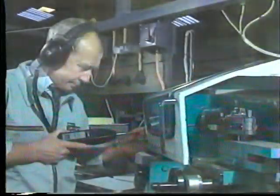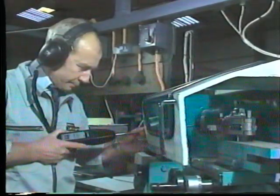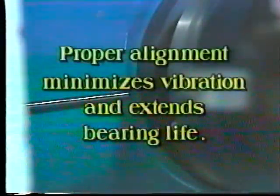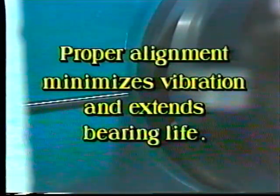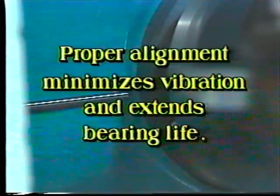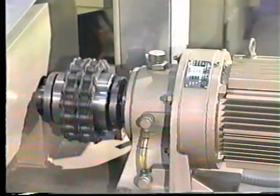One of the factors affecting coupling selection is the speed at which a coupling has to work. High-speed applications usually require couplings that can be precisely aligned, especially when there is an unsupported shaft on either side of the coupling. Both the shaft and the coupling should be checked for vibration, because vibration can cause early failure of bearings, both in the motor and in the driven equipment. Accurate, correct alignment of a coupling will minimize the vibration and extend the life of the bearings.